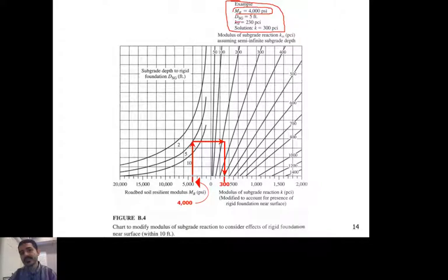And this is the thickness now, for the first time, the thickness of the subgrade. The subgrade is 5 feet, meaning that the bedrock is, again, very shallow, and now the thickness of the subgrade is 5 feet, and K infinity is 230.